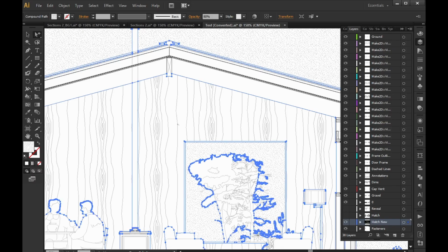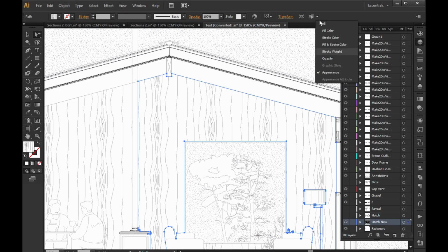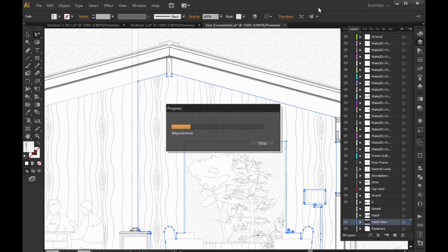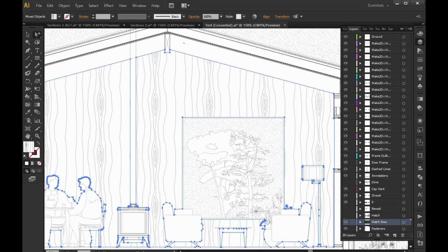And maybe this hatch here. If I do here, I can do Select by Appearance. Yep, click there. You got it. See, it doesn't get the other hatches. It gets how it looks like that. Maybe this is also 80% transparency. I don't want 100%. I want 80 because it's too busy of a pattern. I don't want it to pop too much, you know?